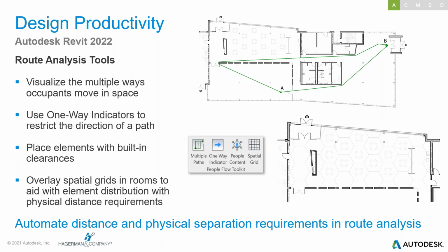To control the 4 new tools visibility, you'll go to the Options User Interface Route Analysis tools and just turn off the checkbox if you don't need them, or leave them on just in case. It is on by default for your information there. So basically, if in the past, if you needed to turn off a certain tab on the ribbon, that's where you go, Option User Interface. There's now a checkbox for this tool. But like I said, I usually just leave it on.